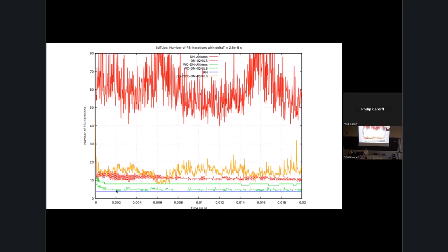And in this case, once the time step's small enough, the Robin approach is really efficient. If you have a very small time step, the Robin approach takes exactly 5 iterations for every time step, so it rapidly converges. The way the Robin approach works, some assumptions it makes only make sense for small time steps. So in this case, this smaller time step ran faster than the larger time step, because the larger one was taking 50 iterations and this was only taking 5. So a smaller time step can actually make your overall solver faster in FSI.